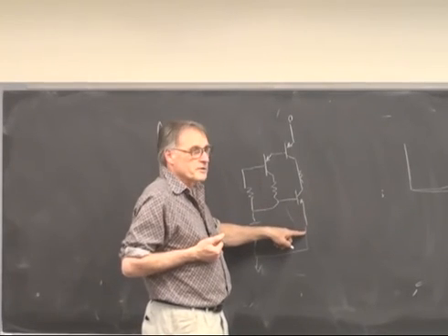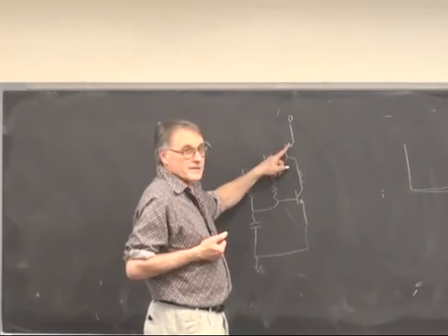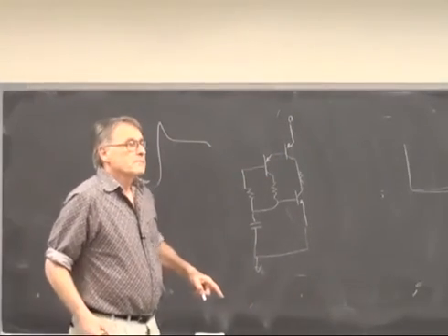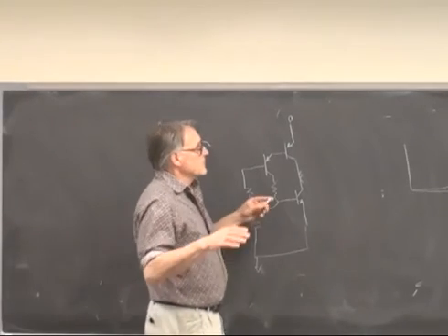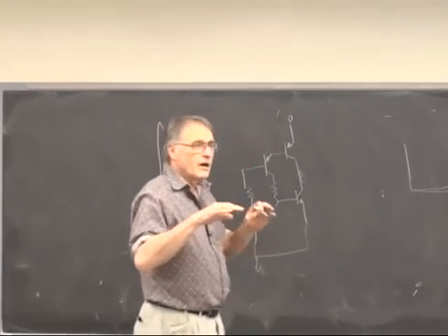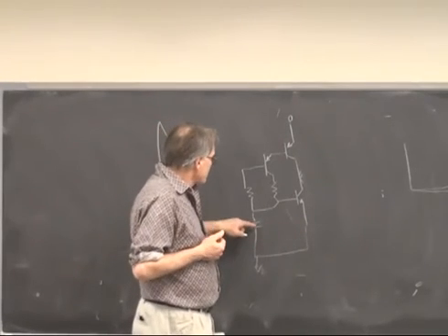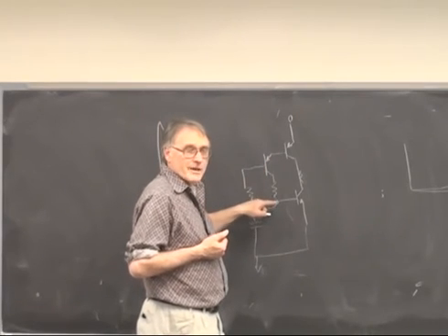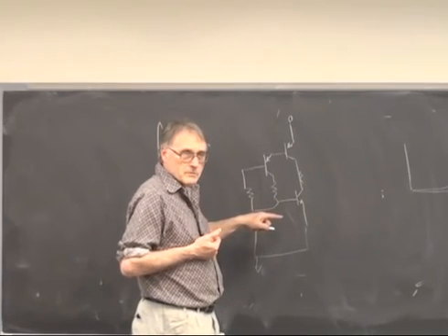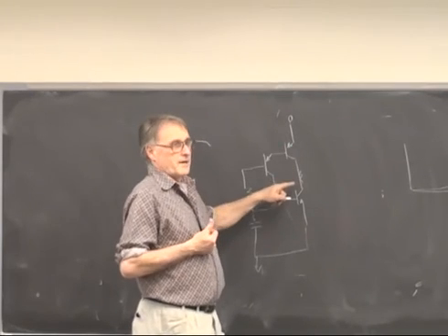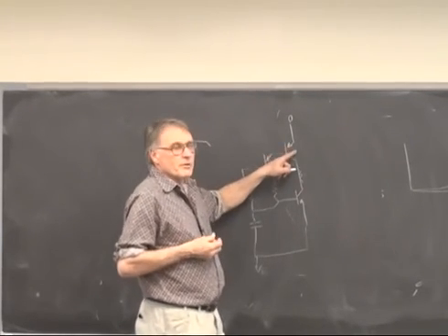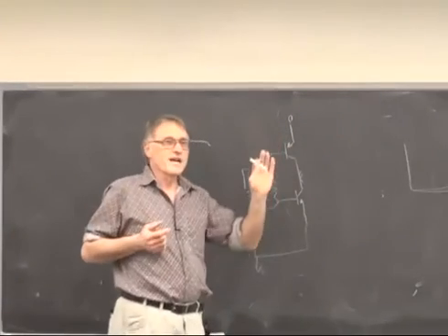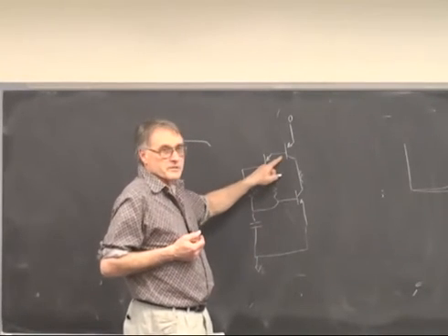As soon as this transistor turns on, wait a minute, this transistor's on, this one's on, a lot of current flows. And the system then hovers at 0.7 plus 1.4, which is about 2.1 volts. And it stays there until the voltage drops below 2.1 volts, at which time all of the current stops, because now one of these transistors is going to cut off.